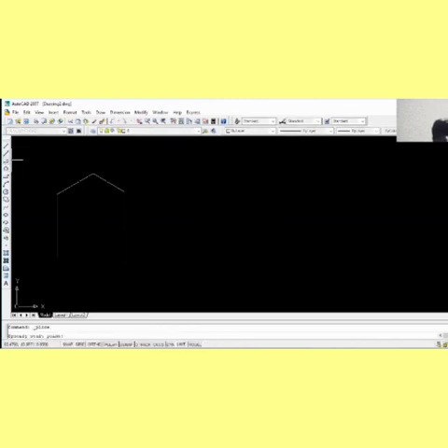Okay, now let me take my polyline command again. I can choose this. Now specify a start point. I can decide to come here. After coming here, I can decide to change the size of the width or the size of the thickness of the line. So now I click W, enter. The starting width, I can use 0, enter. So I push enter. I can use an endpoint. You can see it's now saying specify endpoint. So the endpoint, let me use 2.5 and then enter.